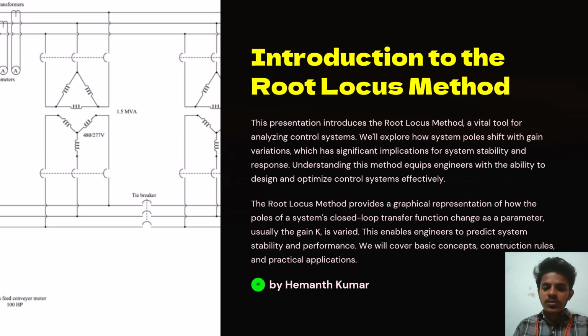The root locus method provides a graphical representation of how the poles of a system's closed loop transfer function change as a parameter, usually the gain k, is varied. This enables engineers to predict system stability and performance. We will cover basic concepts, construction rules, and practical applications.